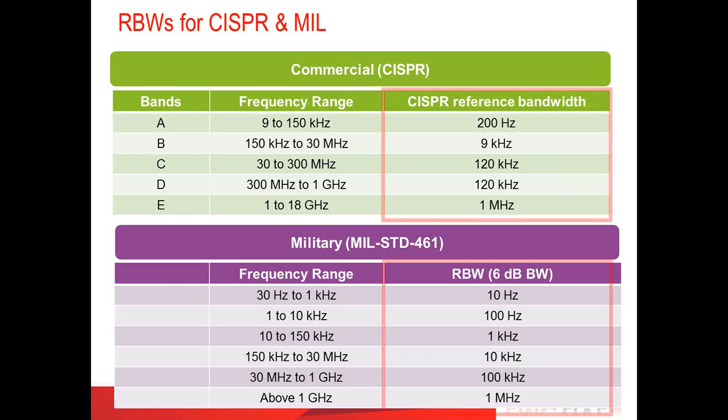But what is happening is that as the signal goes through the attenuator, our signal-to-noise ratio is decreasing. Since signal level is constant, the only thing that can change is the noise floor, and the noise floor is going to increase as the attenuation increases. That relationship is, for every 10 dB of attenuation that you add, you're going to see a 10 dB increase in the noise floor.